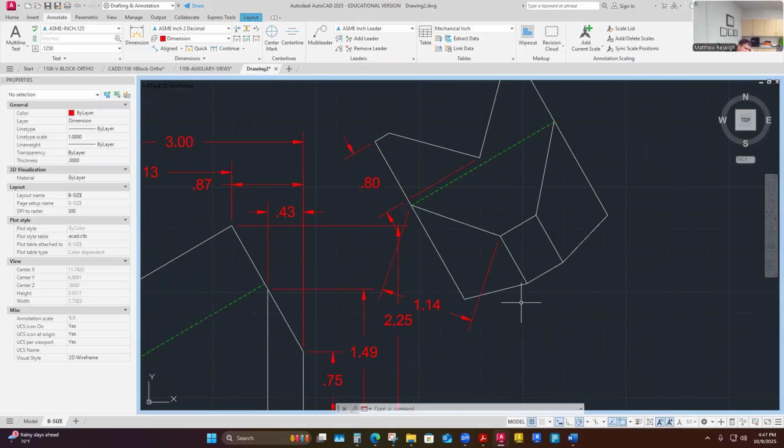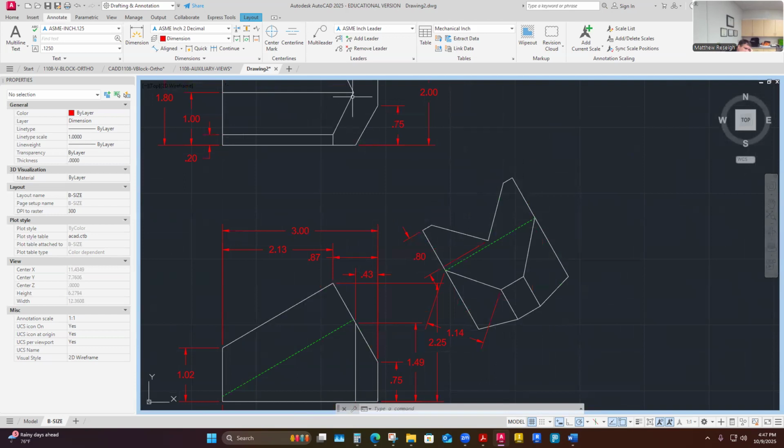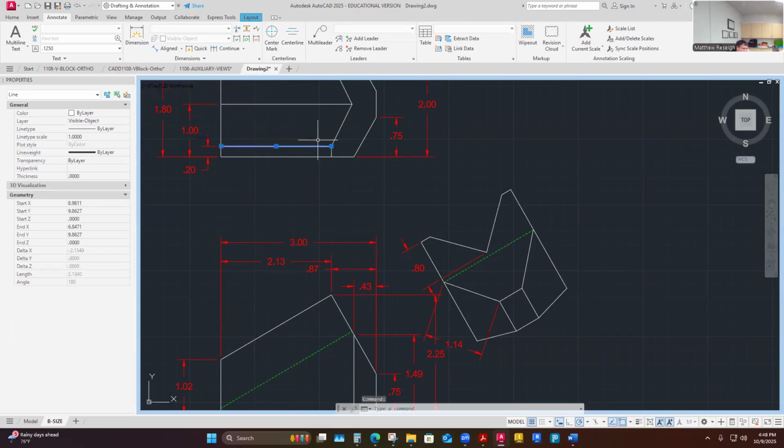And then that's the V. The V has some other dimensions, except this part of the V and this part of the V are all foreshortened. So if I'm looking at the V as a trapezoid, have I been able to determine all of its lengths? Well, I've got this one, 2.13 is doing some of the locating and size work, kind of point to point style. The 1.02 and the 2.13 are helping me establish this line of the V surface trapezoid.